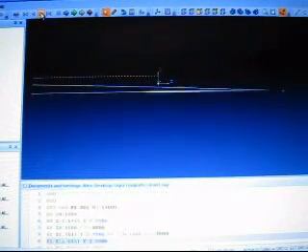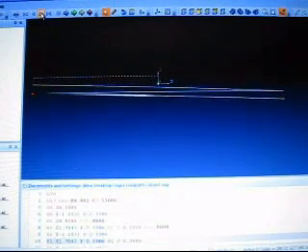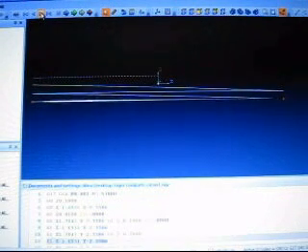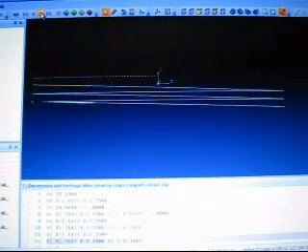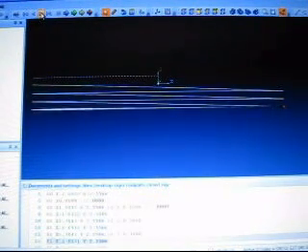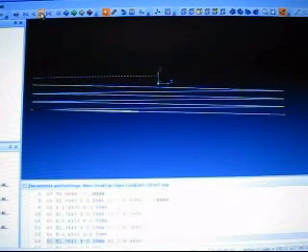Next move, we're just going to come right back. And it's going to be cutting material, realize that. And it's going to cut down, ramp down another 1/10 of an inch. And then come back, and then ramp down another 1/10 of an inch, and come back, and then ramp and cut down another 1/10 of an inch. Okay, now at this point I could take it back just to complete that cut and to my final depth,